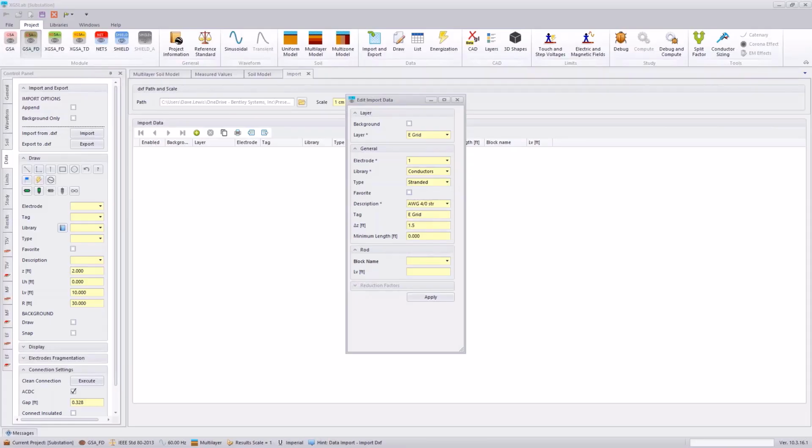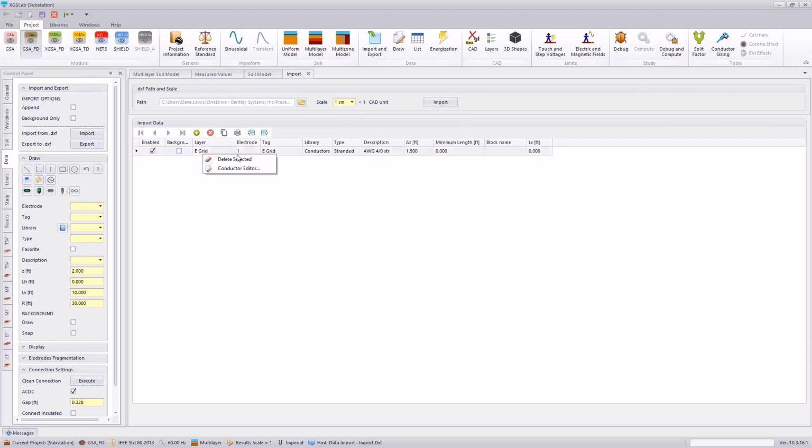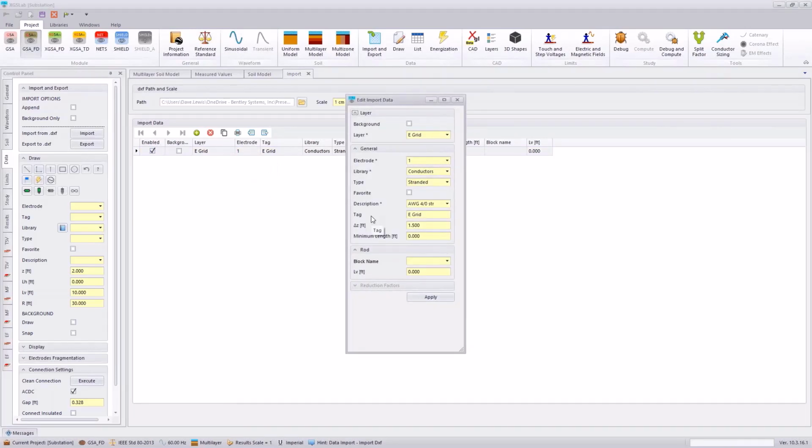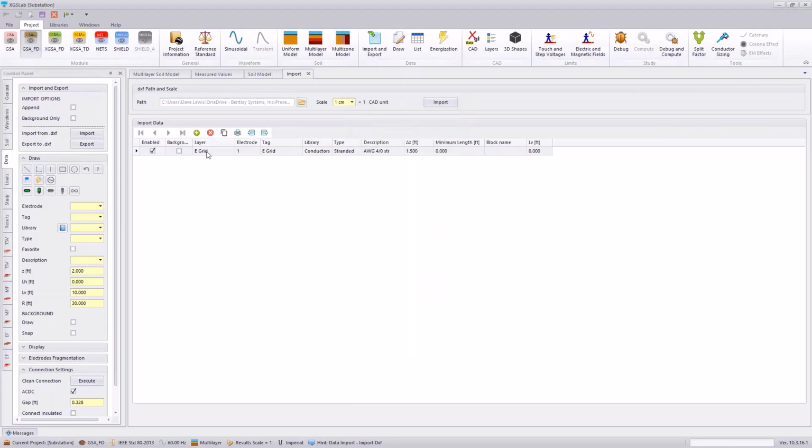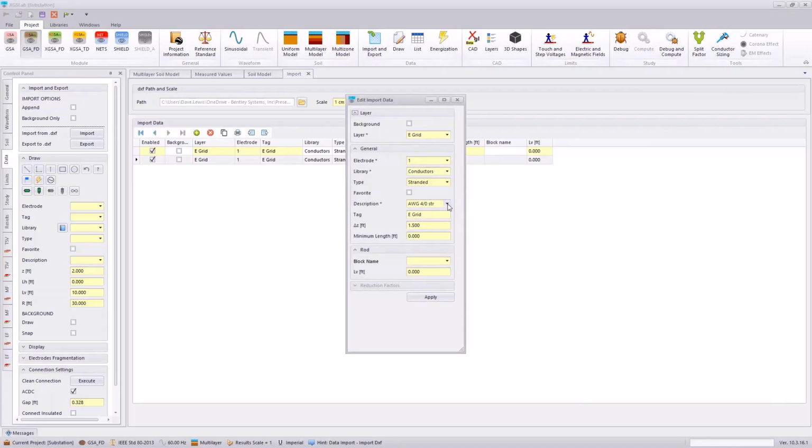And I do need to shift this into the earth for my analysis because typically if you're getting these drawings from a CAD package, part of these transfer voltage analyses is bringing in information from different resources. So combining those into CAD is relatively convenient for being able to do a study with XGS.